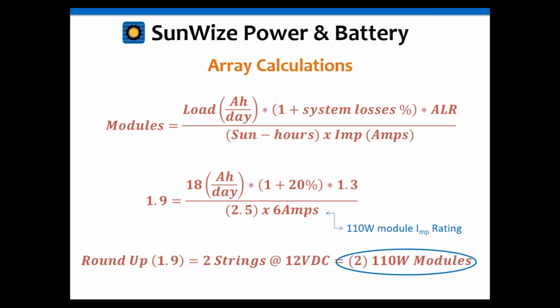If you're finding that that number ends up being small, like 0.2 or 0.3, you may want to go to a slightly smaller module to bring it back down so that you're more around the 1.8 or 1.9 or whatever. Or if you've gone bigger, it could be 3.8 or something like that, or even a 0.8. But again, remember you always have to round up. You can never round down. Very important, because if you round down, your system will be too small, and it's going to fail.